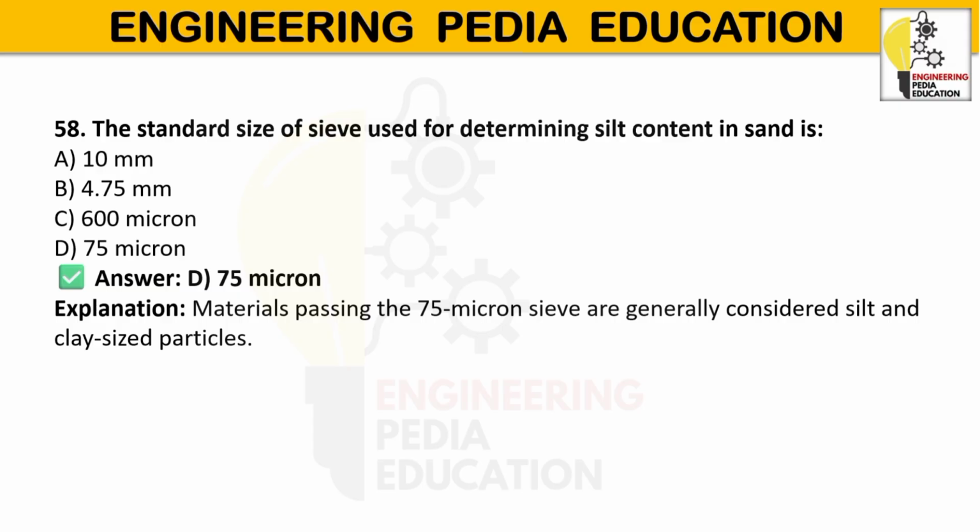Silt is the percentage of very fine particles present in sand. Excess silt reduces the bond between cement and aggregate, increases water demand, and lowers concrete strength and durability. For sand, a silt content of not more than 8% is considered good. Generally the jar test is preferred for it. It's given in IS 2386 part 2.